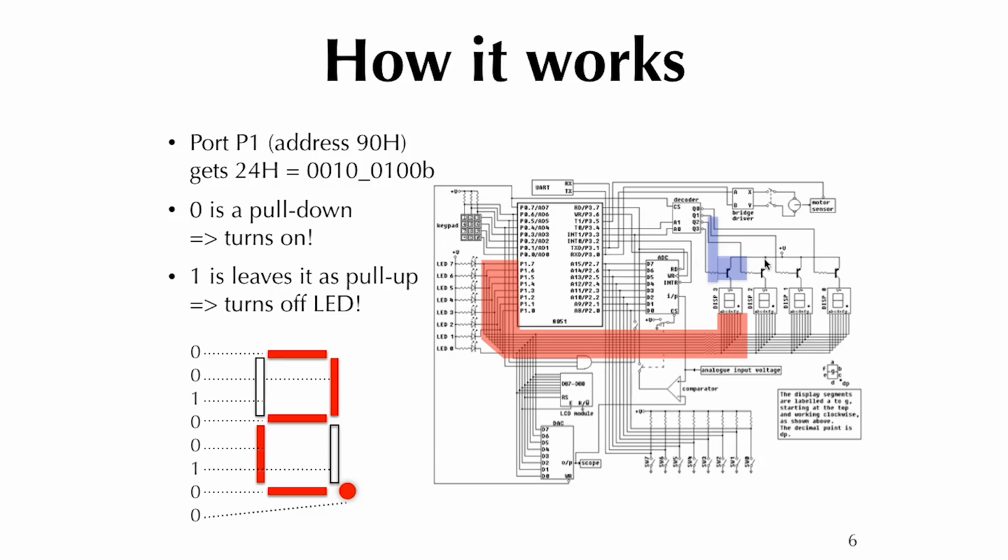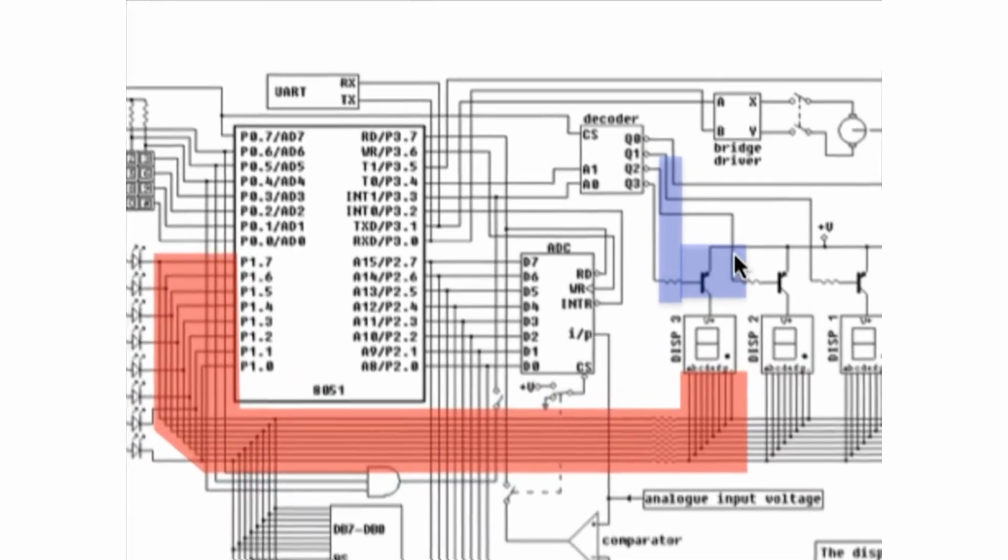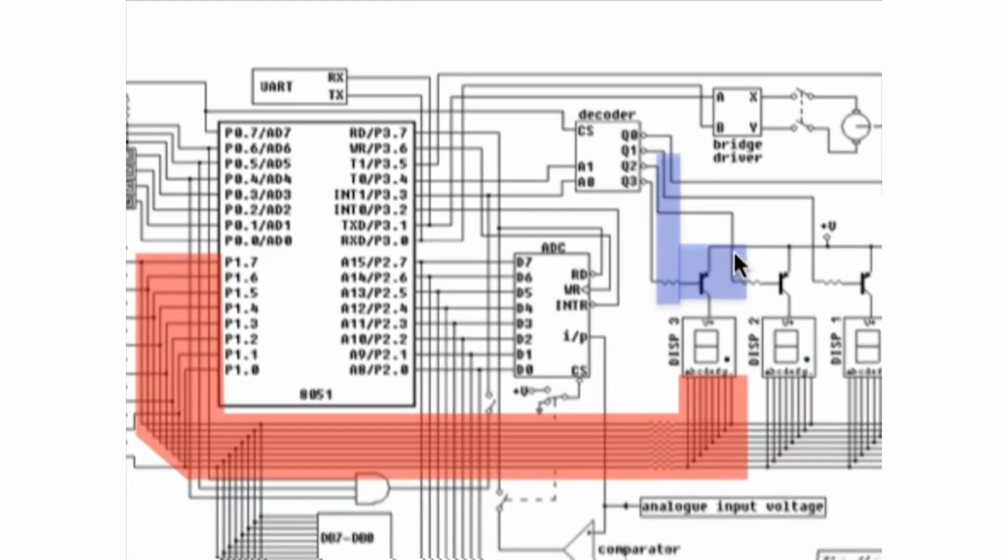Instead, you do the opposite. If it's outputting a 0, what does that mean? That means the processor or microcontroller connects to ground. That's easy. I don't have to drive so much value. I don't have to develop so much current, right? I just have to connect to ground. And so that means a 0 is so much easier for a microcontroller than a 1.